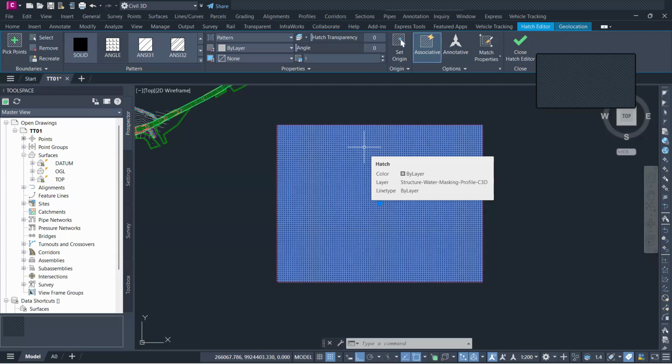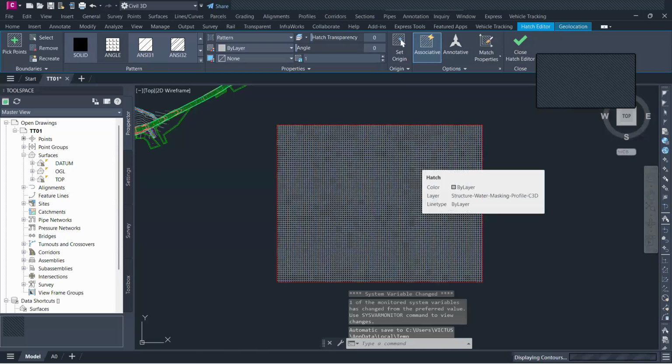So after day one, before we open the section the next day, the surveyor is going to come on site and pick levels for the entire site again. Once we have that data, we will prepare it the same way you prepared for road design in Civil 3D, and then you're going to import them and overlay them on top of this design. So we will create a surface for that day. So this is how you create that.